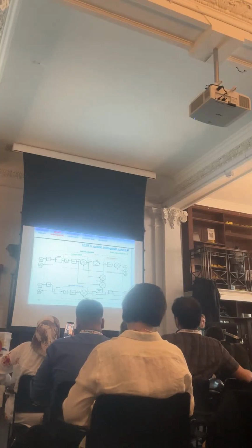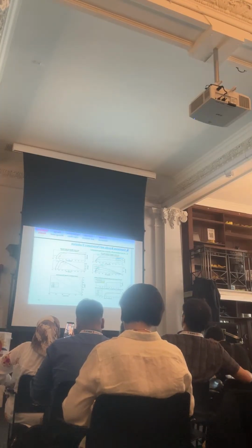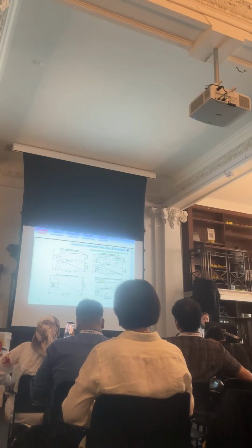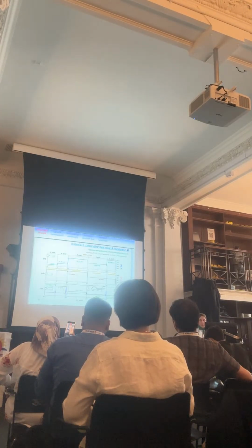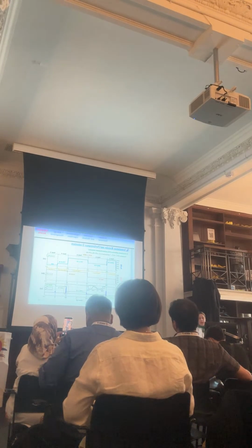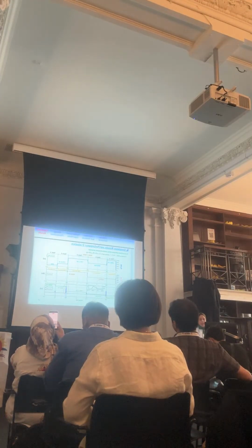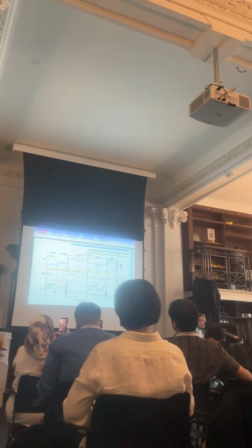Now let's move on to simulation results. The slide presents the validation of the PV array, the battery and supercapacitor models. The simulation responses closely match the expected electrical behavior under dynamic conditions. With these models validated, let's move to dynamic scenarios, functional validation, with five operating phases that simulate variation in solar irradiation and load demand.